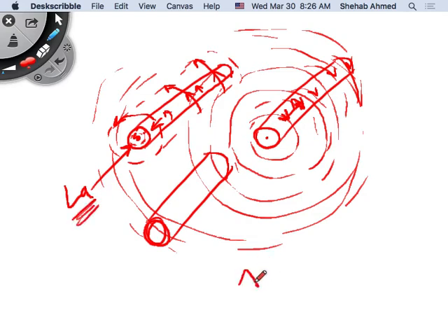So inductance of phase A is equal to what? The total flux linkage, right? When it was alone, it was flux linkage due to that conductor, right? But it's not alone anymore, right? It's in a space with many other conductors, right? So I would like to calculate the total flux linkage of that conductor, and then divide it by the current flowing through it, then I calculate inductance of phase A.